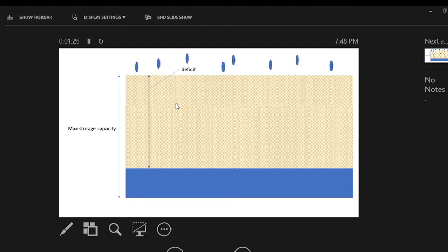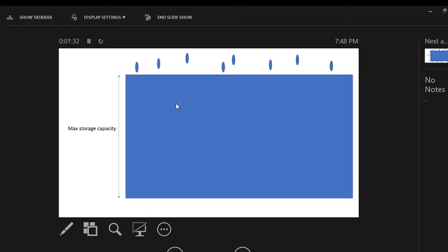As we start to get more rainfall, and if we get enough rainfall, then we will completely fill our soil layer, meaning that we have no storage left and it's completely saturated. We don't start getting percolation out of the bottom of this layer until it is completely full and we are having rainfall. But once that occurs, we do get that, and that was the percolation rate, or the constant rate, that we had put in. Now, if we continue to get rainfall, our storage capacity is completely full, and we're getting more rainfall than the percolation rate, then at that point, we're going to get runoff.